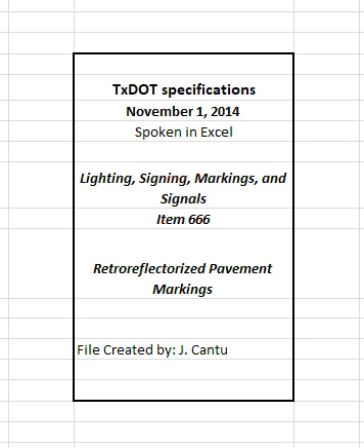If markings are placed at contractor option when inclement weather is impending and the markings are damaged by subsequent precipitation, the contractor is responsible for all required replacement costs. 4.3.1 Type 1 Markings. Place the Type 1 marking after the sealer cures. Apply within the temperature limits recommended by the material manufacturer.